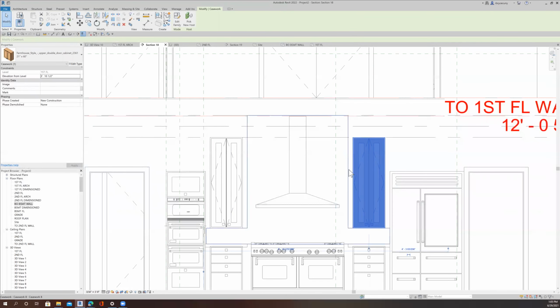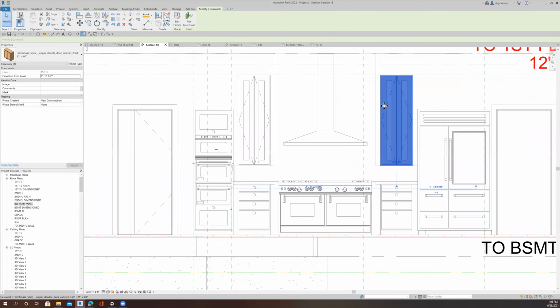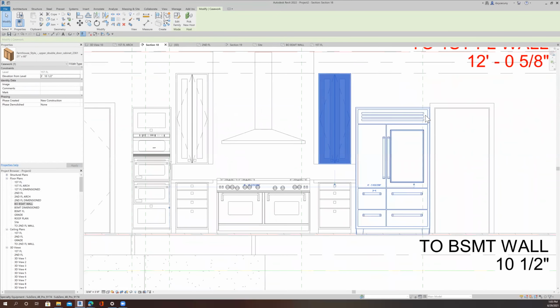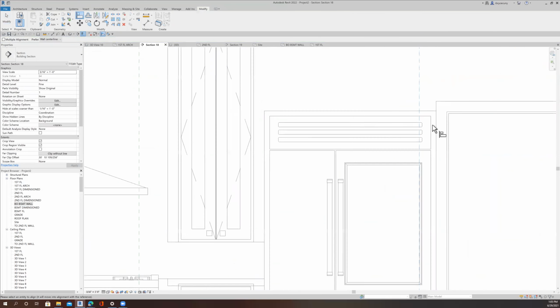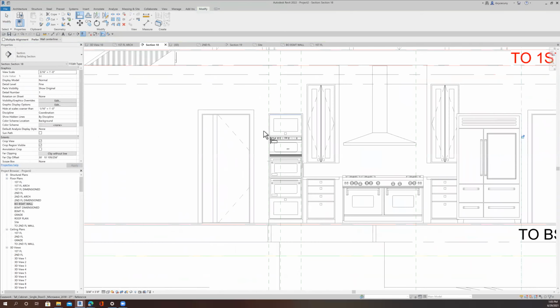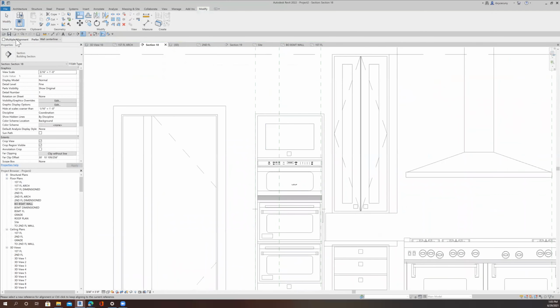Okay. My backsplash will have to change a little bit. My countertops will have to change a little bit. The center line of that's going to change. So let's do this stuff one at a time. So first of all, I want to align to this reference plane with this refrigerator. Okay. And then I want this cabinet, looking to see if I clicked multiple and I haven't.